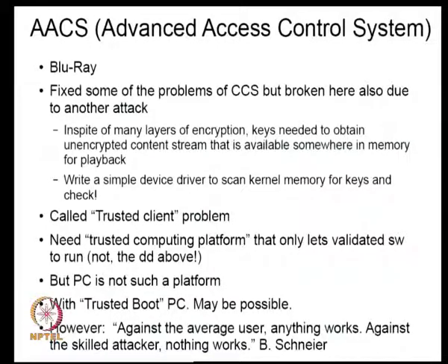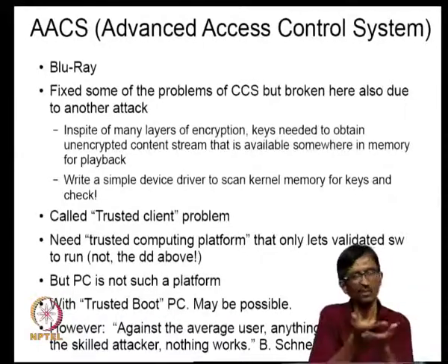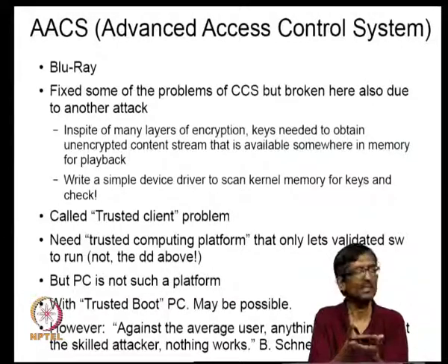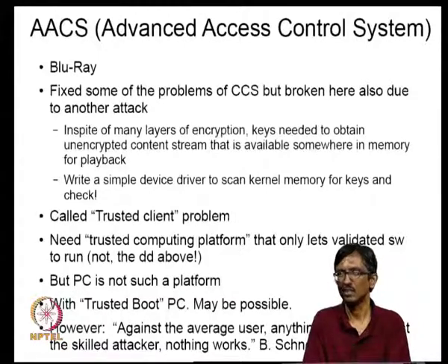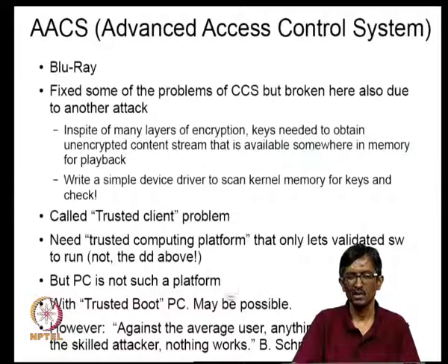We discussed tamper-proof storage already. Basically, it is the kind of storage sitting in a chip where, even if somebody scrapes it off and tries to look into it, it will destroy the information. That's how it is designed. So there will be tamper-proof storage at the chip level, and it will hold some of the hashes that are to be allowed. These hashes can be inserted or taken out by some specific mechanisms. If you have that kind of platform, then you can essentially avoid these kinds of problems. But currently there are very few platforms which have this property.